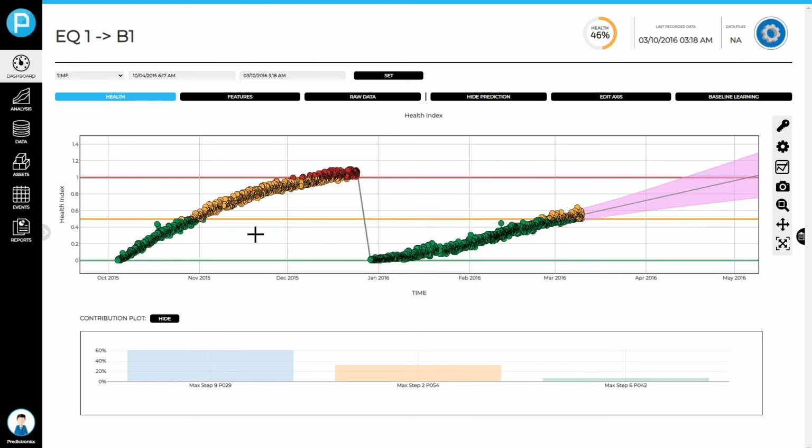As you can see for this application, October to January, that was 3 months or so. You can see that this system is telling us we probably have another month and a half here. And with this information, now the maintenance technician can make decisions to decide, okay, let's say I have a PM cycle in April. Do I just replace the part when the PM cycle goes, or do I wait and see, okay, can I get through another PM cycle with this asset?